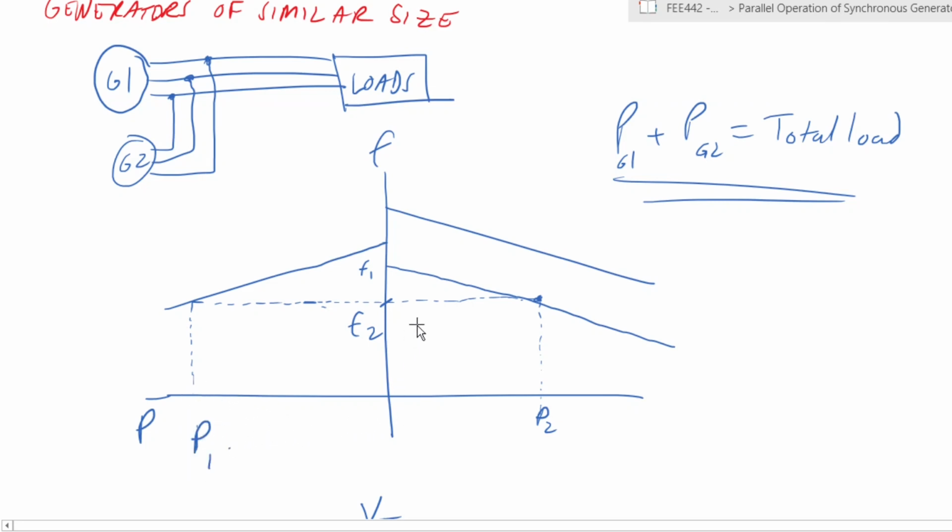So what do we do? Yeah, you want your frequency being constant, but you want to change. You want P1 to produce less, say, you want it to come here, say P1A, right? So let's see how that would look like and what we would have to do to achieve that. Okay, so what we want is we want to retain them at the same frequency, but you increase the value of power being supplied. So this means that you would then have to change both set points.